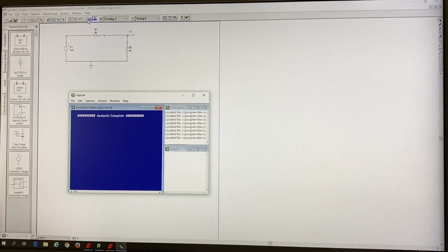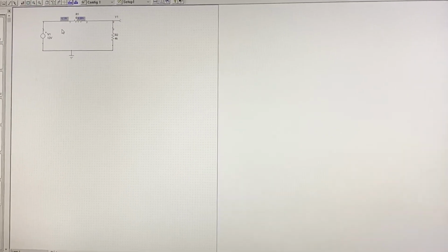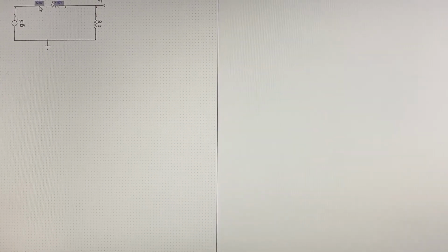So I have to click here where it says, can you read that? I can just minimize this so you can see one thing here. It says refresh op values. What this menu does is that it shows me the voltage drops in my circuit if they were correct. So I'll just click on it. Then it's saying node 1 has 12 volts, and node 2 has 4.8 volts.